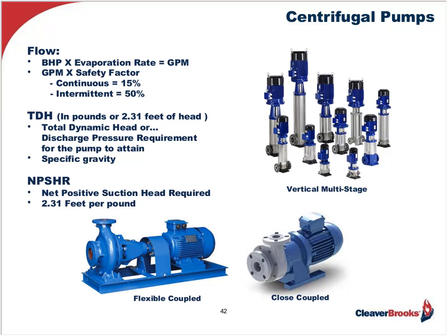Now, at the same time, we need to determine the NPSHR, which is the net positive suction head required for the pump to keep it from cavitating at the duty points that we've selected.